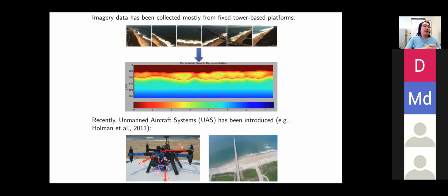Basically, you take the boundary condition of the wave and the bathymetry elevation and use the hydrodynamic model, and you can reproduce this wave phenomena, wave propagation. Then you get the wave information, wave speed, frequency and wavelengths. Then based on this, you invert this wave phenomena to get the bottom bathymetry.